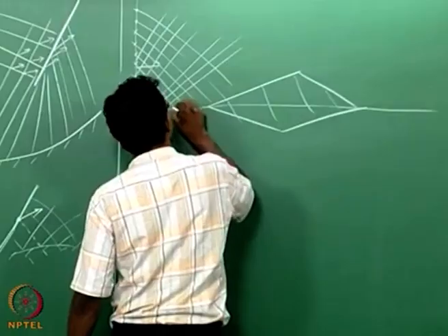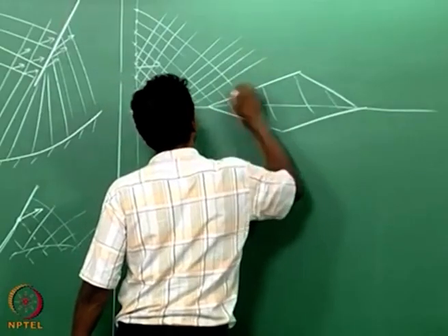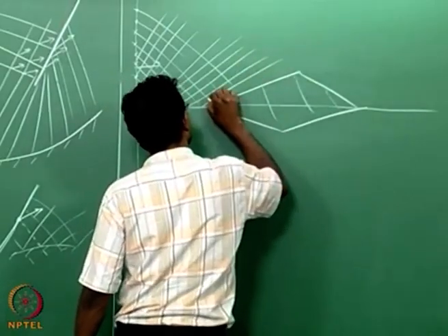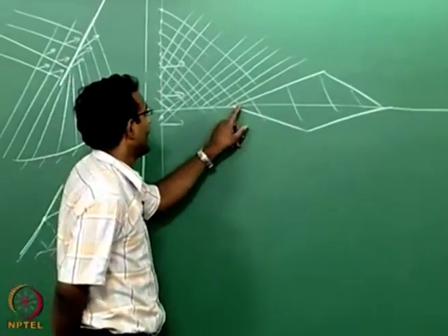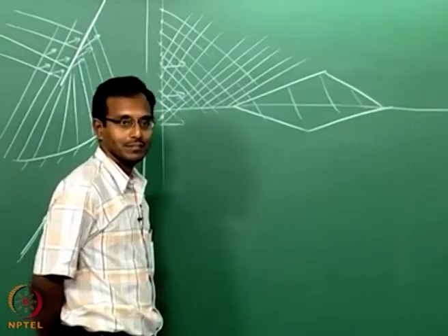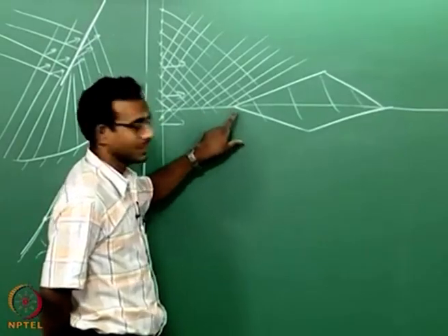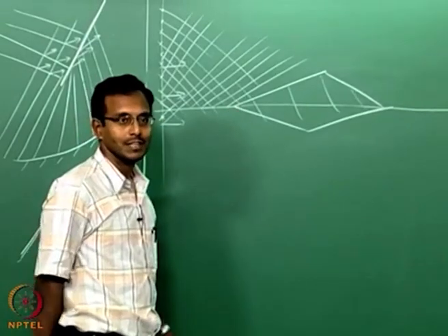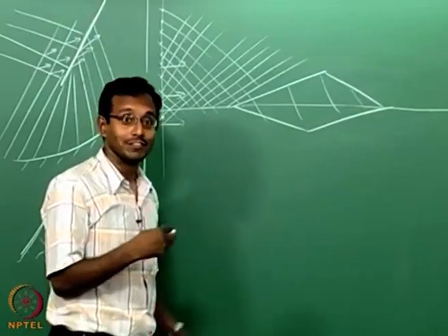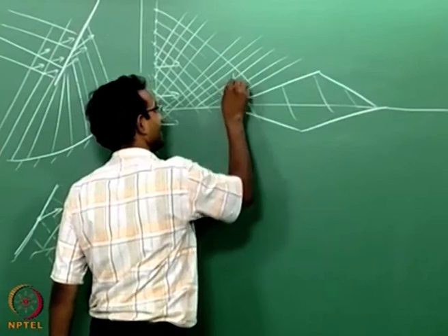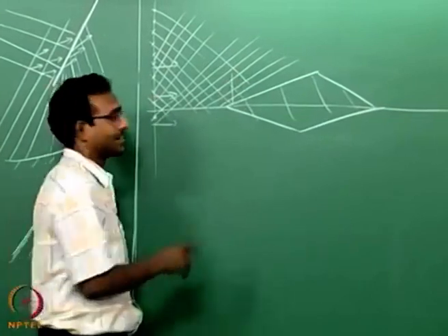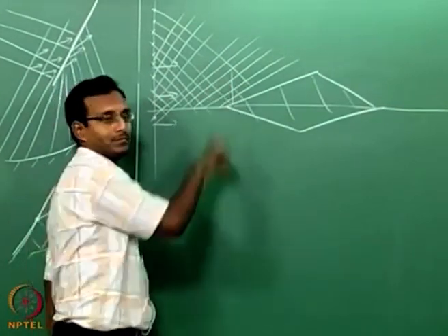Ideally I should not be talking to you about this now, it should have been given to you in some other fluid mechanics course. Okay. But I will go to this point, suddenly I have to give a wall condition there. Till now it was a symmetry line, suddenly it is a wall condition. If I just go and start solving with the wall point condition there, you will start having characteristics crossing. Characteristics will just bounce back and go upstream.